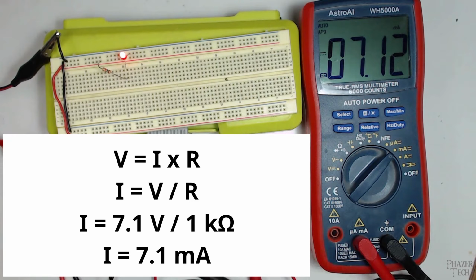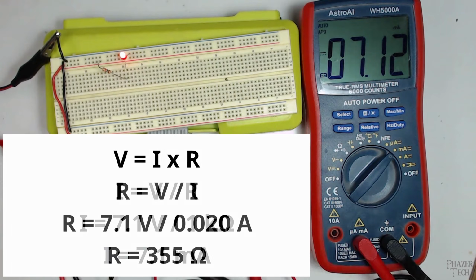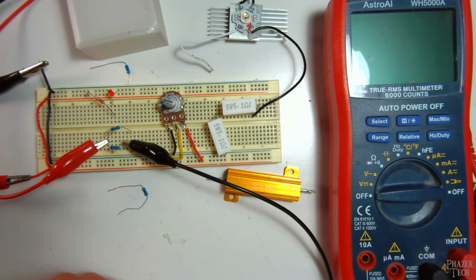But this LED's maximum current is 20 milliamps. We can control the brightness of the LED by controlling how much current passes through it, and we can control how much current passes through it by changing our resistor. So let's say we wanted to run the LED at maximum brightness. All we would need to do is enter 20 milliamps into the previous equation and solve for resistance this time. We get a resistance value of 355 ohms. So now I'll replace our 1 kilo ohm resistor with one that's around 355.